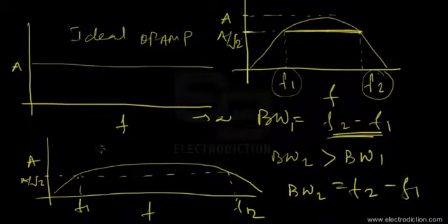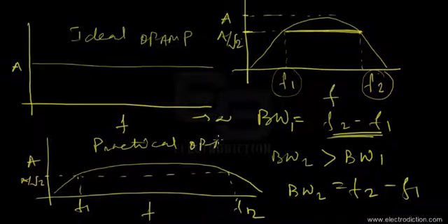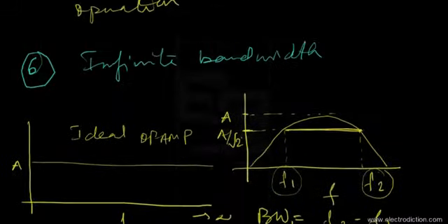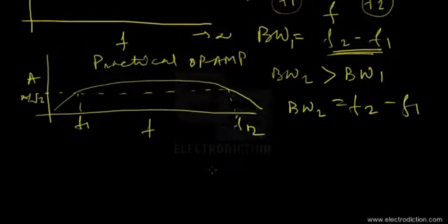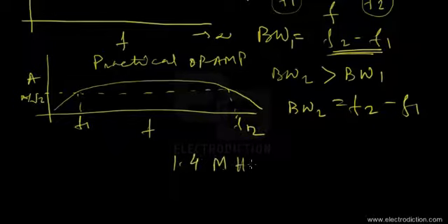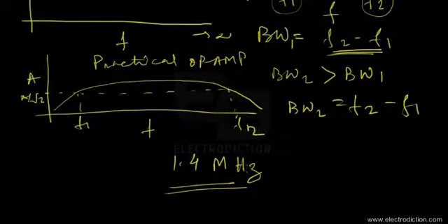So an op amp basically has a quite high bandwidth, as much as possible. For the μA741C op amp, the bandwidth is about 1.4 megahertz. Much improved op amps have arrived today and are being created each day at various semiconductor companies. For the newer op amps, this bandwidth is even higher, as high as about 4 megahertz.